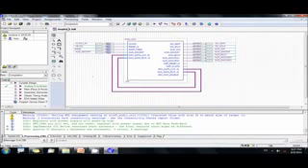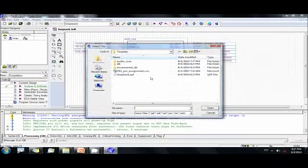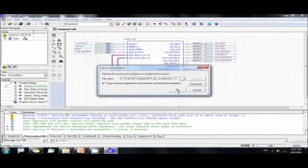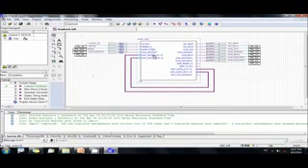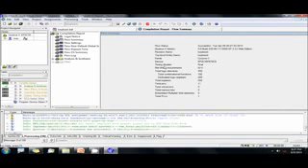On the Courseware main menu, click Assignments followed by Import Assignment in order to import the DE2 pin assignments.csv pin assignment file, and you may start the compilation of the project. You should be able to see the successful compilation report.